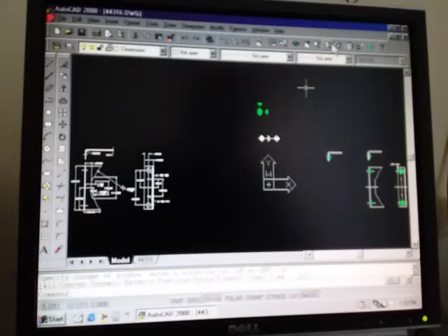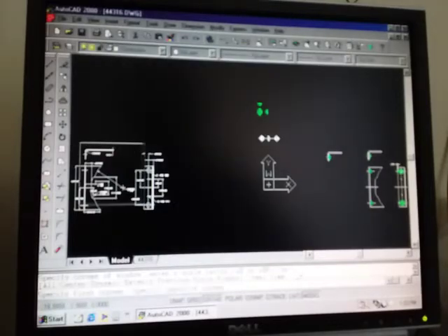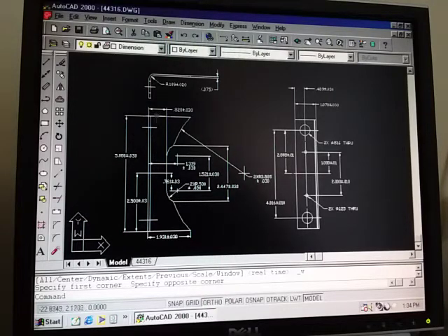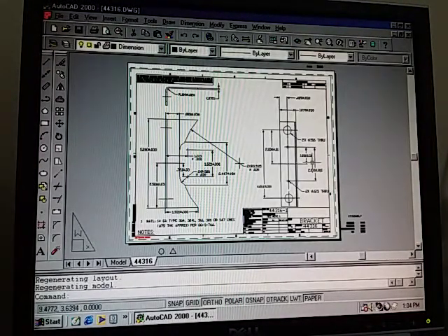Oh, and then once you do the drafting, when you draw whatever part you want to make, you always draw it at 1:1 scale over here. So everything is 1:1. So this 1.93 inches is actually 1.93 inches. So this is 1:1 scale. And then once you made your part and you dimensioned it, then you bring it into this part here. So this is for printing.